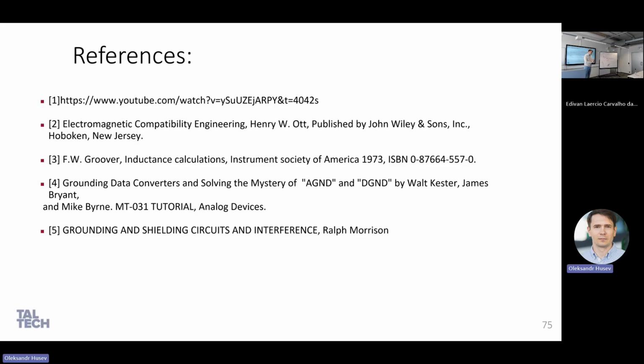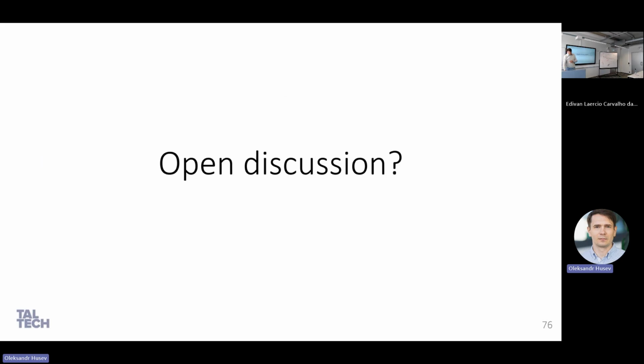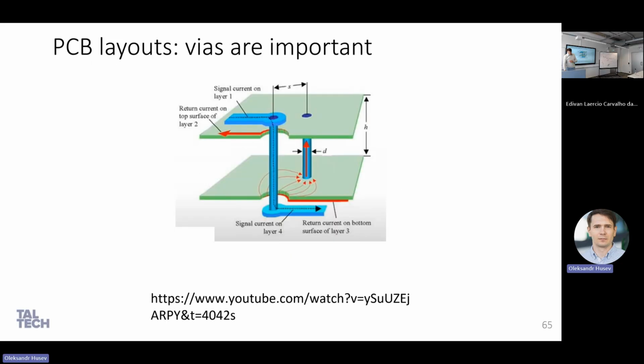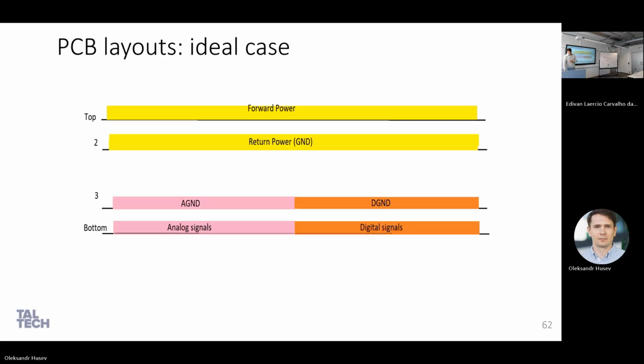If I want to design a double layer PCB, should I put all the ground on the bottom layer and all the power lines on top? Bottom or ground, it doesn't matter in terms of layers itself. What I wanted to show by this picture, this is the so-called ideal case, is that the first and second layers have a very close distance.